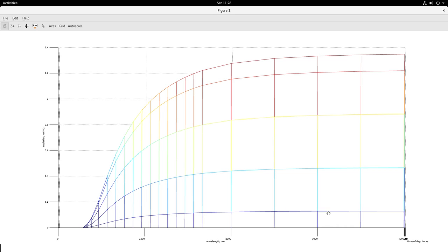This bottom line is at a pretty low insolation, which probably may be morning near 6 o'clock, 7 o'clock, and then as the time increases in the day, you will see the insolation rising further as the time moves towards noon, and probably at noon it may be at the peak value, and then further on it would again fall down, coming down to 0.